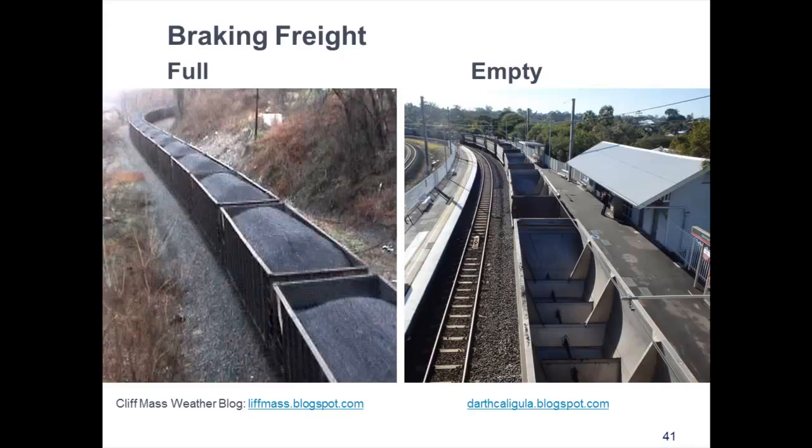Okay, consider this for freight. Compare a loaded coal car weighing 130 tons with an empty coal car weighing 30 tons. The difference is a factor of 4. Freight trains have longer stopping distances than passenger trains because of their weight, their length, and the time it takes for the brake application to go down the train. The train personnel for a freight train must skillfully use braking to deal with circumstances that arise. For example, if a train is on a hill, the front of the train may be on the downgrade and needs braking, while the back of the train may still be climbing the hill.